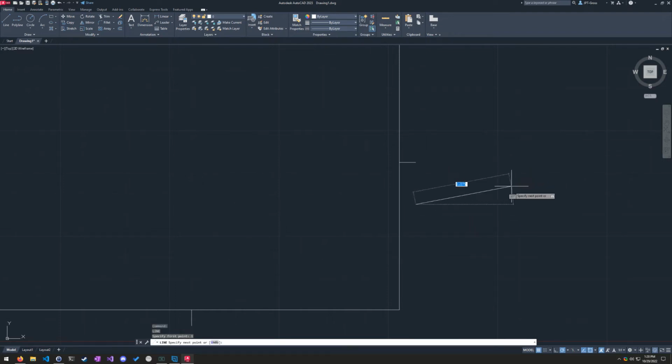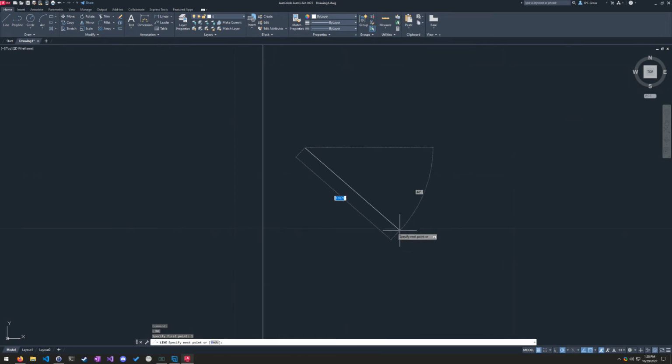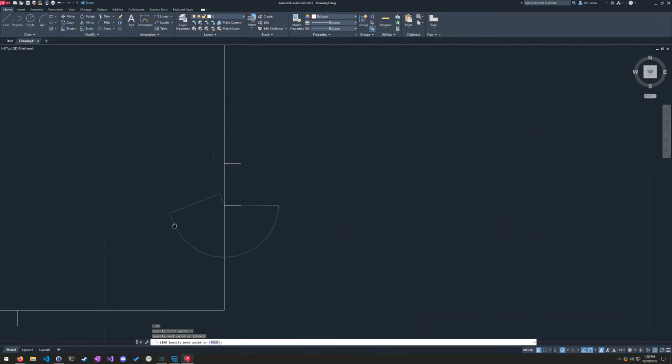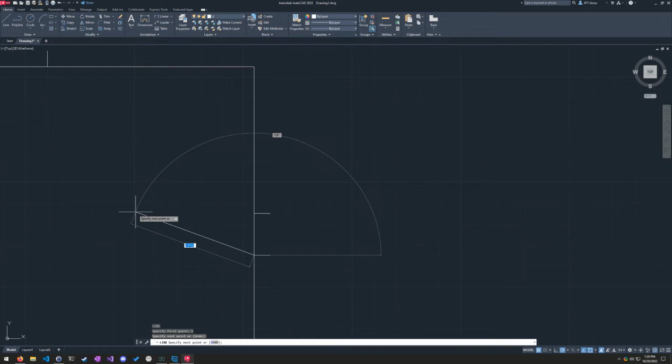And now notice that the start of this line is exactly on the same line as where I dragged from. So now all I have to do, I'll zoom in a little bit, pull to the left, following the green line here, keeping myself nice and horizontal. And when I get back to the border, AutoCAD will snap right to it. And when it snaps, I'm going to click. And there you go. Remember, to get out of the line tool so I can draw my next line, I can just press enter and then enter again to go back.